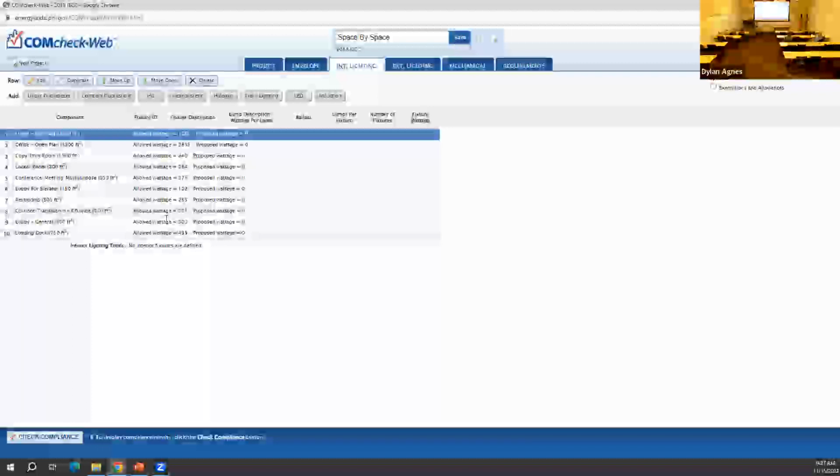You come across any general rules on particular building types where it's easier to use one method versus the other? No, I typically don't get enough data to do that. So it's usually after the fact, we're just doing verification, or energy audits, so we're trying to recreate or reverse engineer the control strategies and allowances and exceptions that people did, so we can verify why ComCheck and the lighting cut sheets and the LPD say one thing, but the utility bills and our loggers say another. So that's a big disconnect between the data sets that makes it hard to do that.